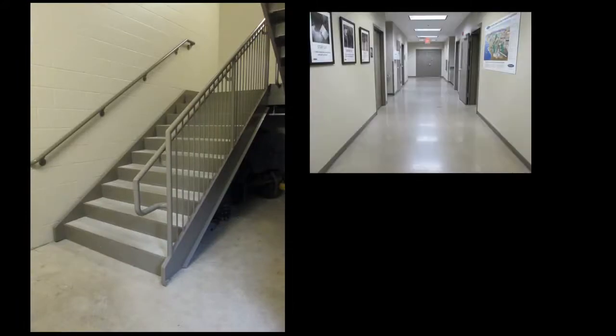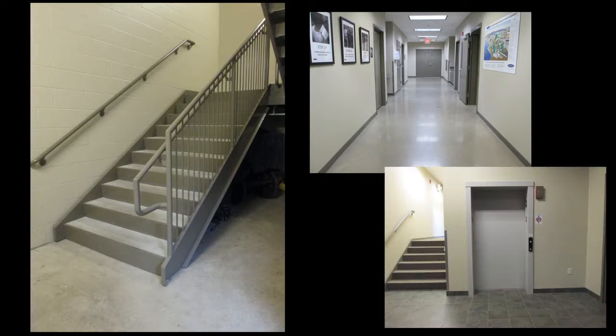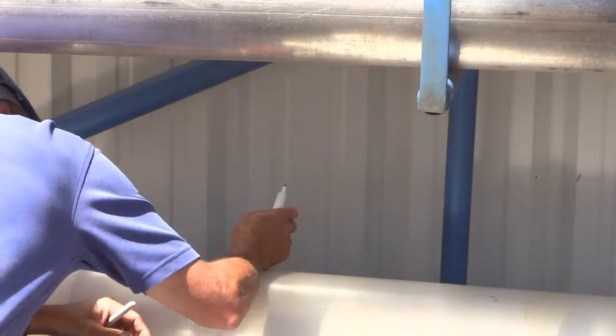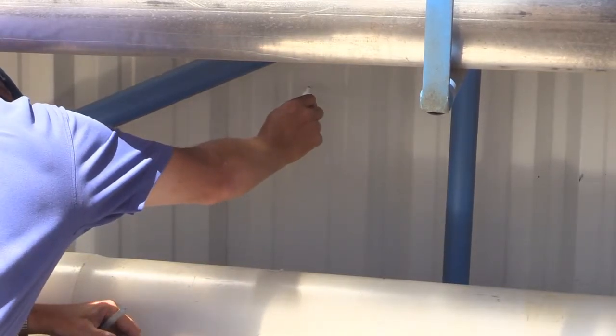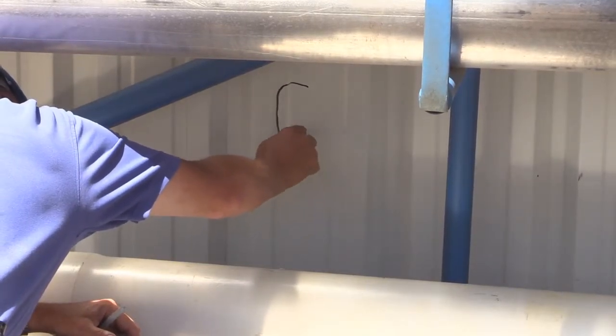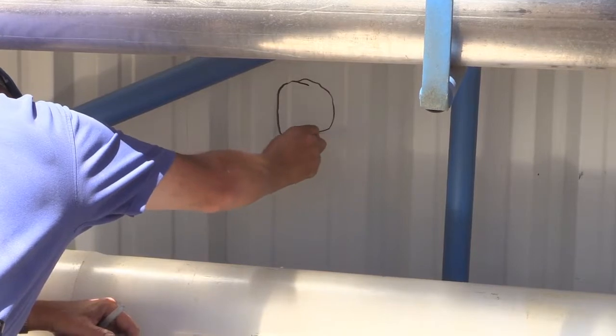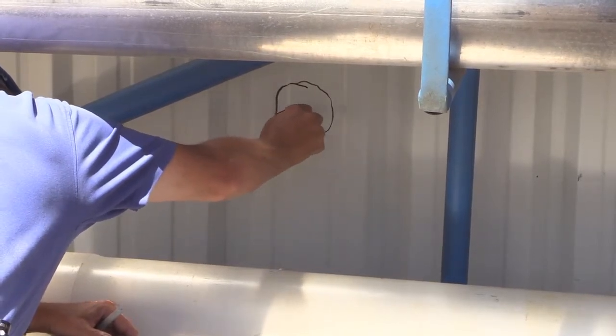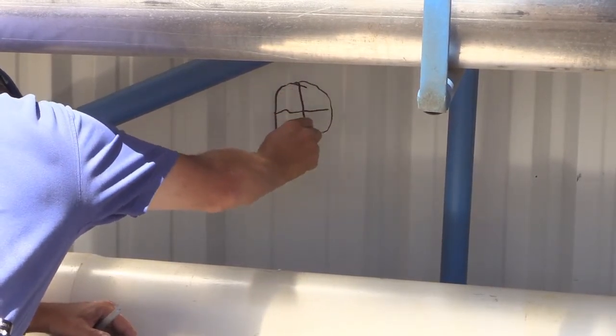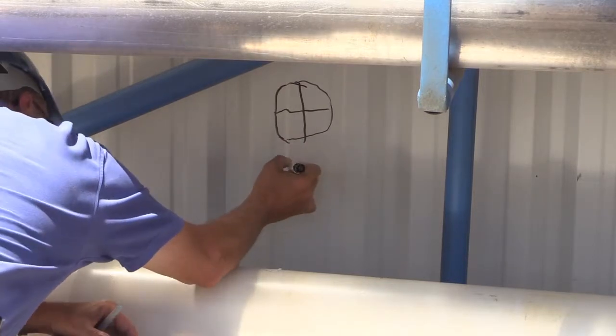Keep in mind also any limiting factors such as stairways, hallways, elevators, and other obstructions that could cause issues with the moving in place and installation of the pipe. If wall penetrations are made, it is valuable to mark these locations with a permanent marker to allow the installation team to know where the entrance point or pass-through points were designed.